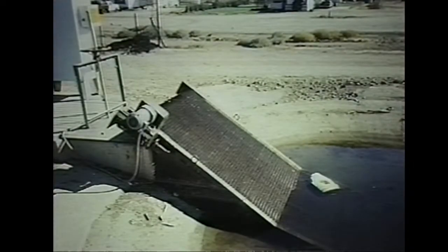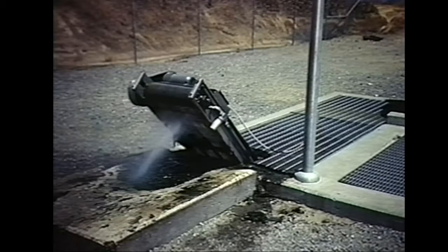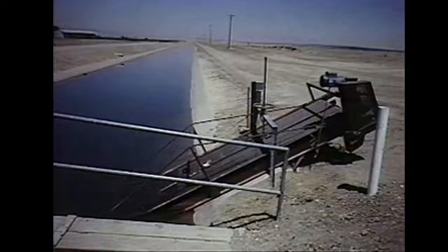For many installations, a pre-filter design uses a flexible conveyor-type belt. These units are self-cleaning and are very effective for removal of particles with a diameter of greater than 1/2 inch. As the belt rotates, the trash drops off the belt either by gravity or with the help of a downward pointed spray nozzle assembly. The trash is not only removed from the belt, it is also removed from the water supply. The belt rotates a certain distance on a fixed time interval, or in response to a difference in water levels on each side of the screen.